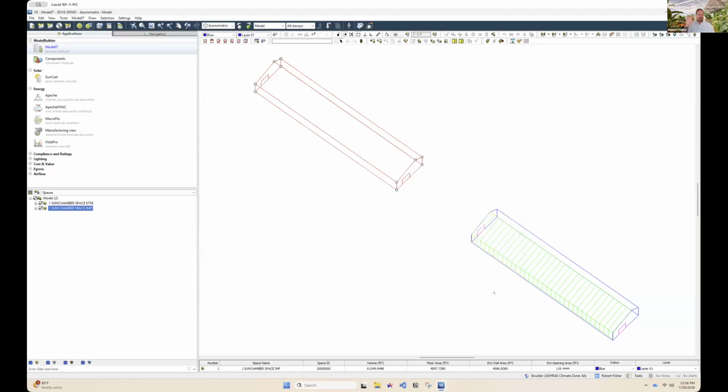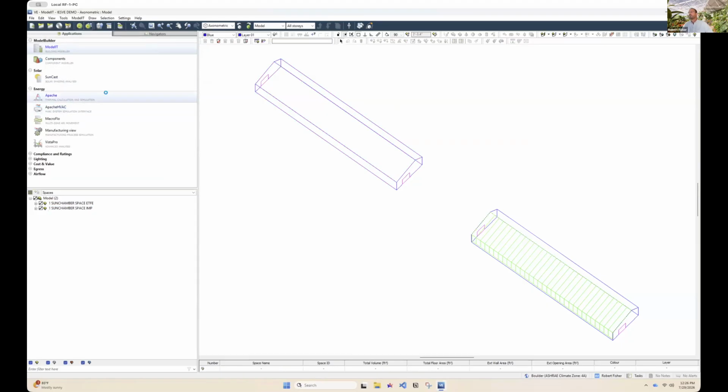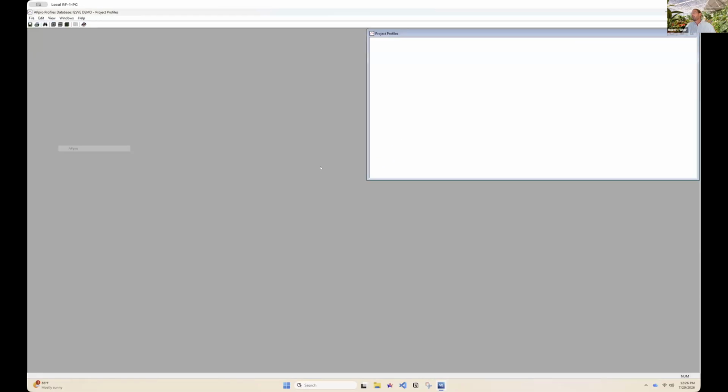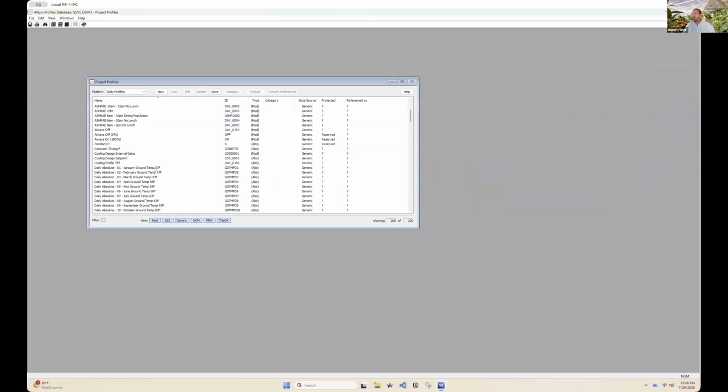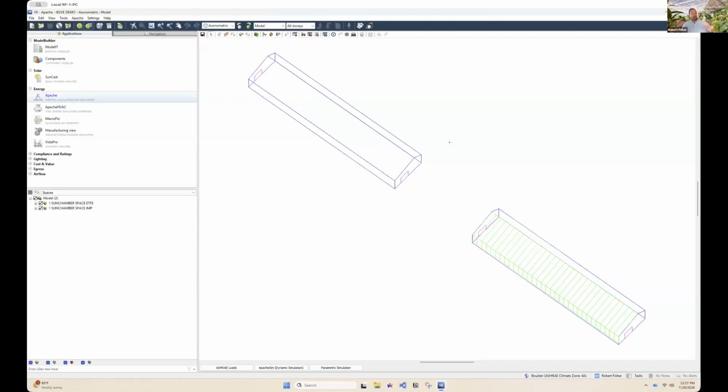So whenever you put different things into this project, you then would go set how it would operate under a schedule, which is going to be down here. It's called AP Pro, and all of these are different schedules you can generate. There's a couple different versions of it. We're not going to go through how you do that, but that's how we're able to allow things to know when they're going to act or not act. Plants transpire more when the sun's out and it's a sunny day and they're getting water. And at nighttime, they do transpire some, but it drops down. So we apply the loads at the correct point in time of the day.